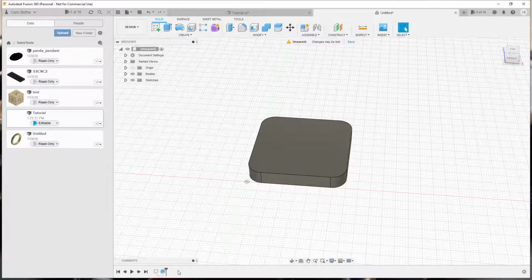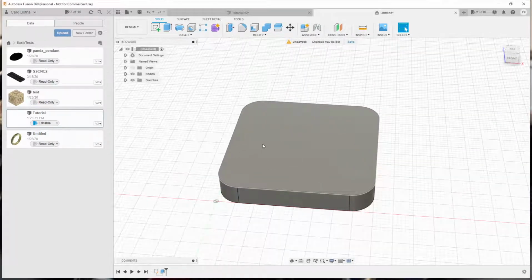Okay, everything that happened after this point would update with it. So that's parametric modeling. Alright, get used to it, because it's probably the way that most CAD is going. Okay, so we've got the outside line. We now want to come in a little bit, because we want to leave a little flat area for the chamfer, and we want to do a little inset.